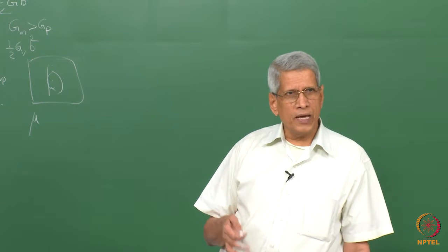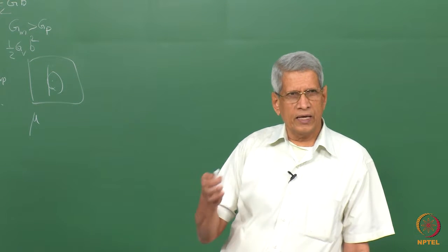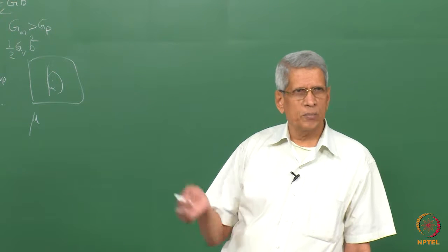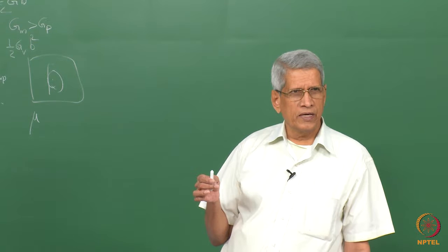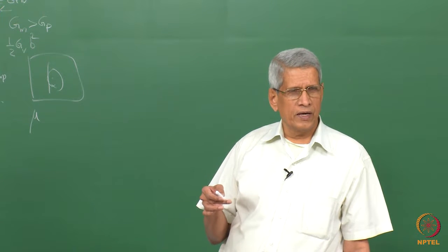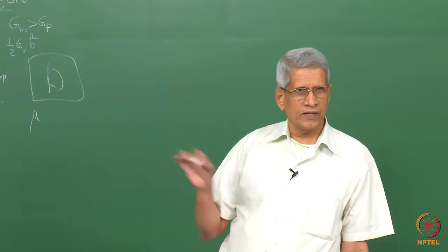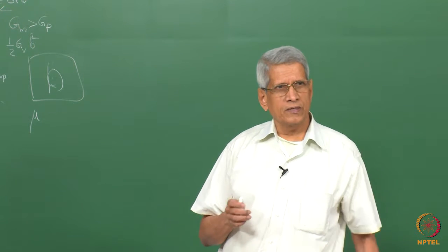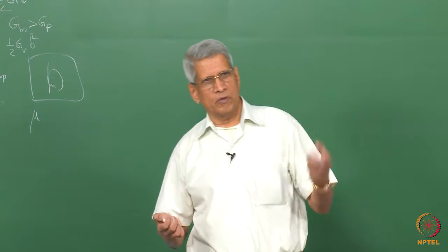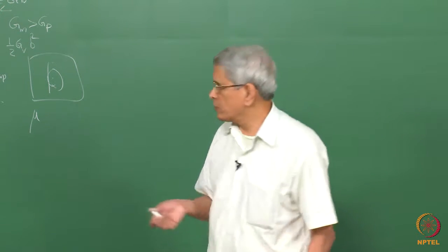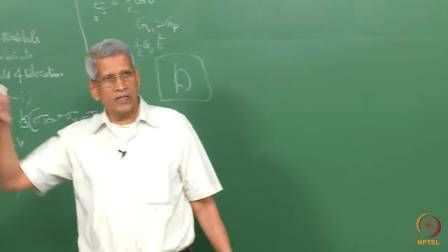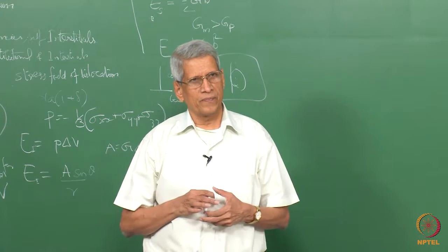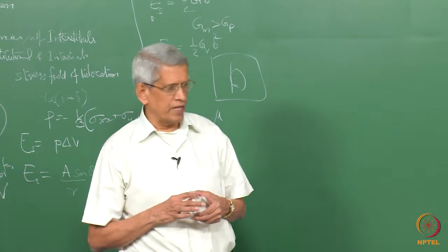Quite often a defect could be anisotropic also, like in iron. When carbon goes to an interstitial position, it occupies a position which is anisotropic, where the defect has a symmetry which is essentially tetragonal. That means that in some directions the misfit will be small when the carbon atom sits in the cage. In another direction, along the c-axis, it is going to be large. The strain will be large in those directions.